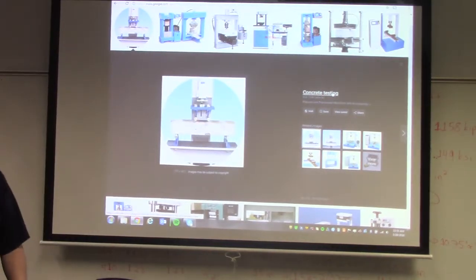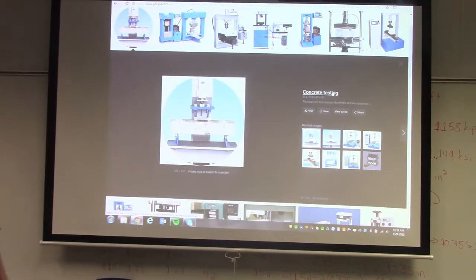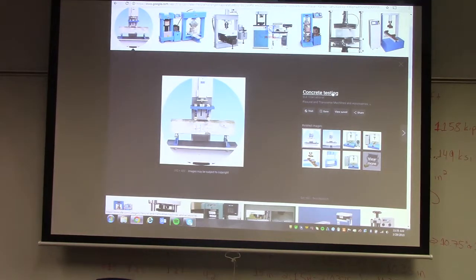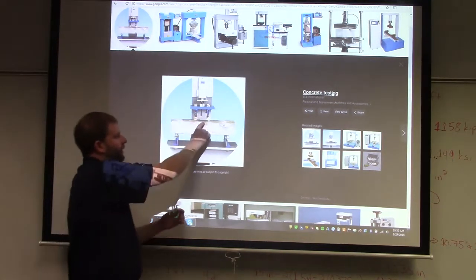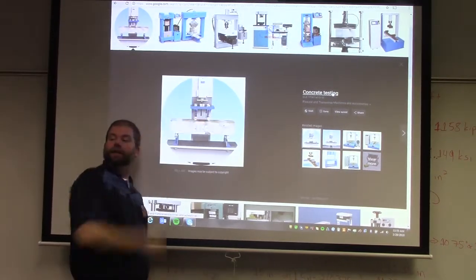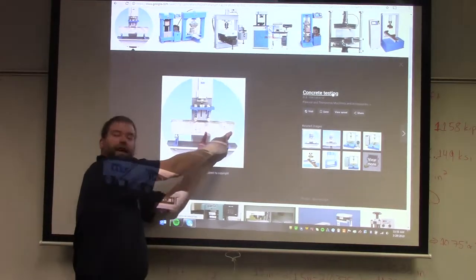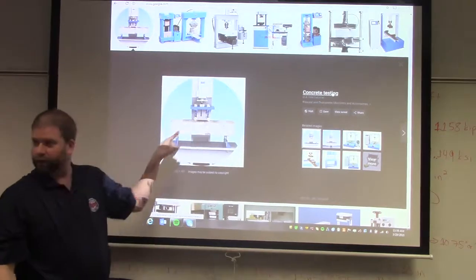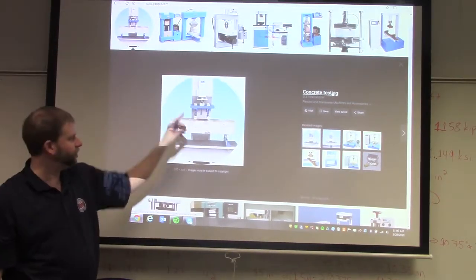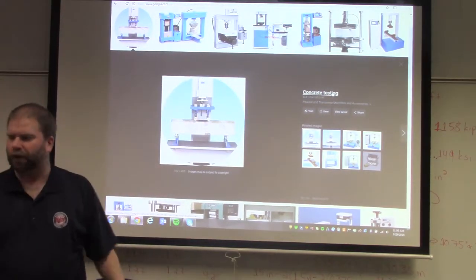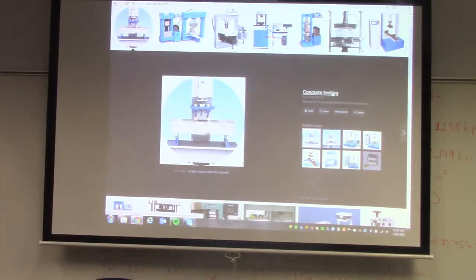Where do you measure the beam, say it's like this, from here or from here, or a midpoint? Say that again. So are we measuring from the end to where? So you would measure, yeah, so your width would be from this point of the broken face to the back, on the back side. Oh, okay. Does that make sense? Yeah, we're not measuring this. Okay. We're just interested in the width, which is going into and coming out of the frame of the machine, and then the depth, that vertical dimension. Okay, and we'll review that when we get them into the machine, too.